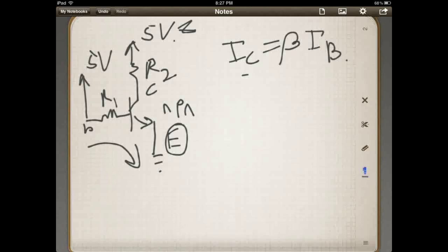Of course, you divide your 100 out, and that cancels, and it gives you 1 milliamp as your base current. So about 1 milliamp of current will give you about 100 milliamps through the collector. So that's how far on you will turn it.